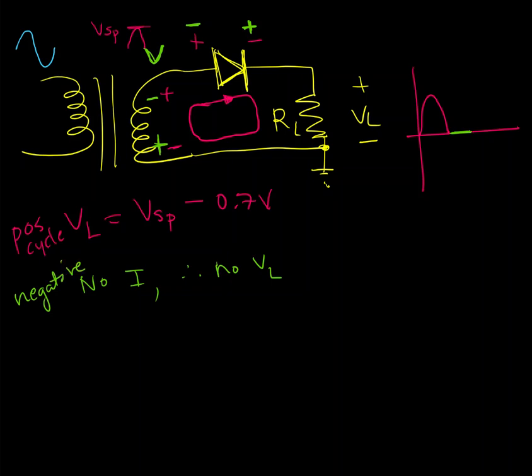And in that way, this circuit converts the AC input voltage at the secondary to a DC voltage at the load resistor. It's DC even though it's a changing voltage, because it doesn't have a negative component anymore. The voltage is all positive. So this is the result of our half-wave rectifier. And it's called a half-wave rectifier because those negative cycles are simply chopped off at 0.